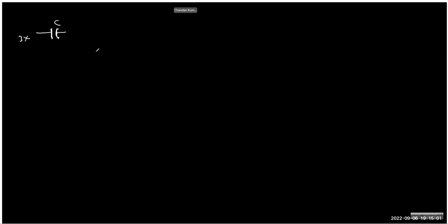Tell me. One answer or two answers you can say directly. If all are in series, if all are in parallel, right? So if all are in parallel, then 3C, and if all are in series, then C by 3. So these two answers are perfect. Now, can we get something more by tweaking the configuration? Like two in parallel, one in series. Do it.